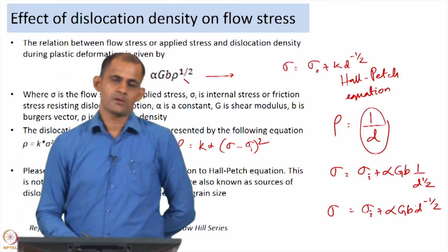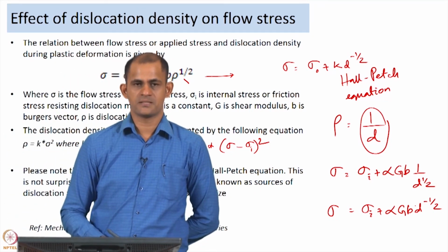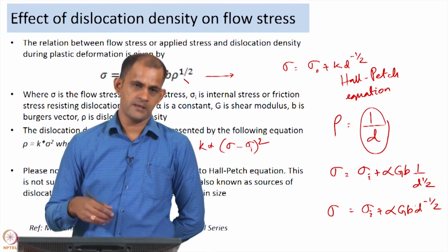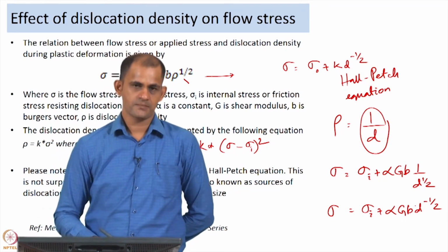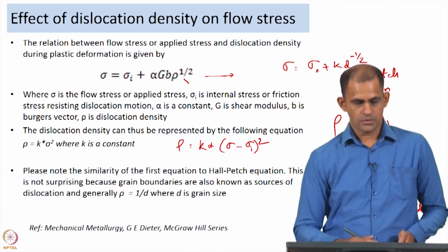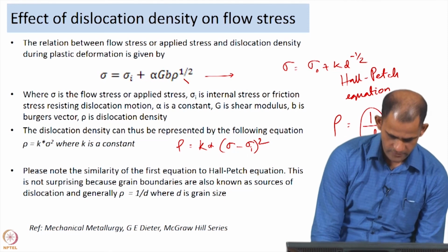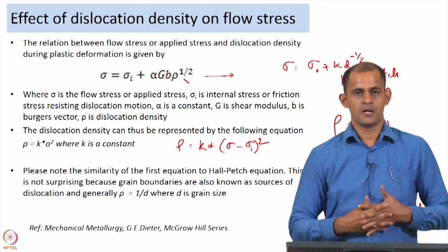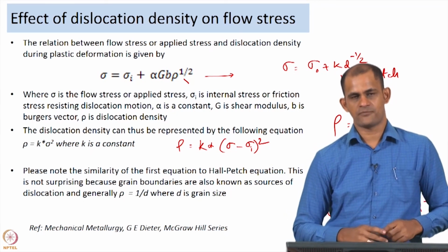Again, the relation between dislocation density and applied stress is something we will use to explain power law creep and to relate strain rate of deformation to applied stress. So, that was the purpose of introducing this concept here. With that I would come to the end of this set of slides. Basically, in this portion of the lecture, I have talked about dislocations.